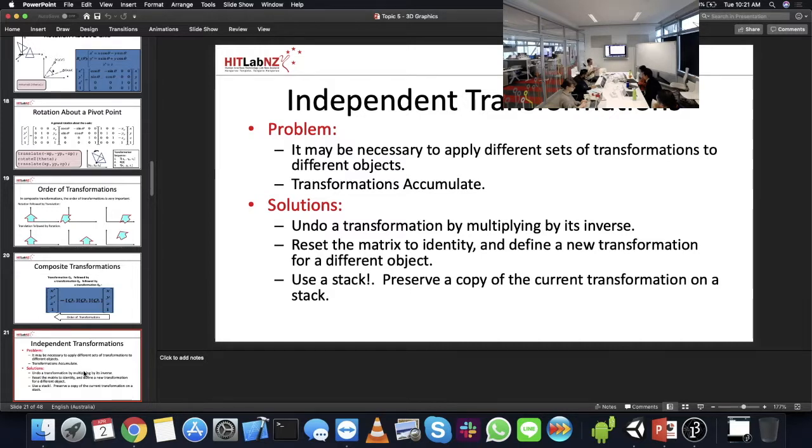But if we want to draw two objects, we have the problem that because everything is done on this world coordinate system, if I start, here's my origin here, and I move this out here and up here and then rotate it in some way, and then I want to draw another one, I have to figure out, instead of where the relationship of this is to the origin, where the relationship is for this to the origin, I have to figure out where the relationship of these two objects are to make sure that when I've moved the cursor here and drawn this, I now know how to get the cursor over here and draw that one, which is doubly hard if this one's moving. So we've seen examples where we have an object which is moving, and every object which is drawn after it will move accordingly.